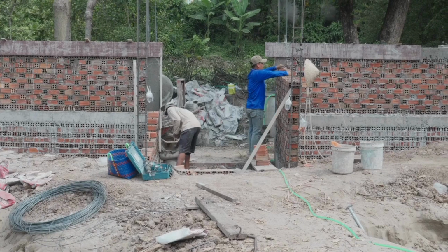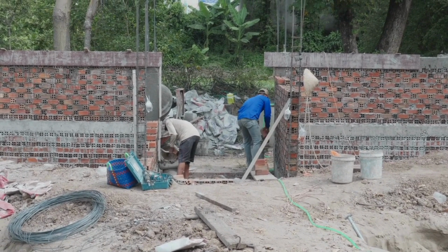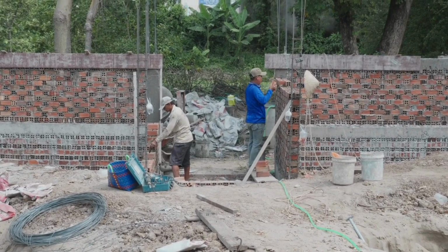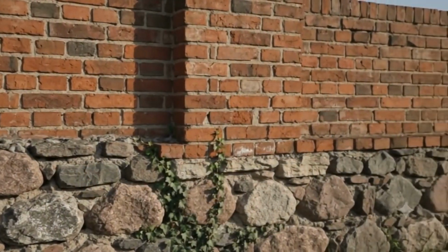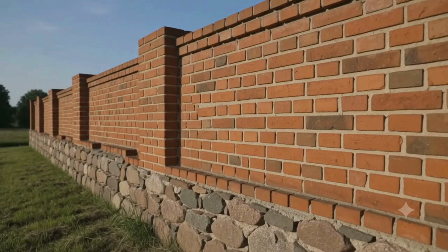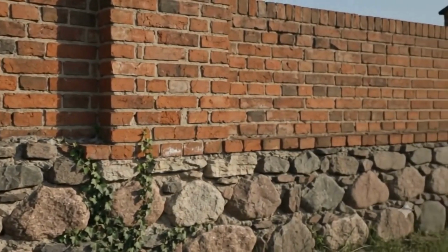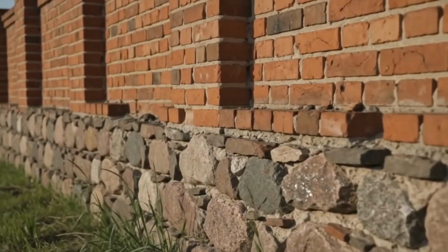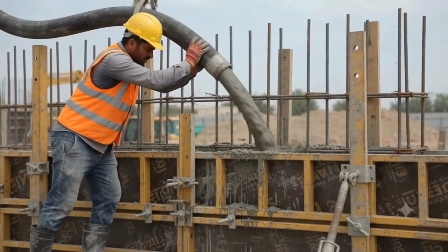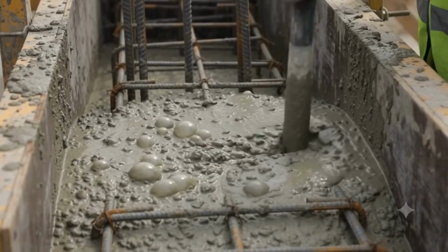For load-bearing walls, whether they are constructed using reinforced concrete, brick masonry, or random rubble masonry, strip foundations can be designed according to the amount of load being transferred to the soil. For relatively light loads, a random rubble foundation may be adequate and economical. However, when the wall carries heavier loads, a random rubble foundation may become either structurally unsuitable or more expensive due to the increased width and depth required. In these situations, a reinforced concrete strip foundation becomes the better and more reliable solution.